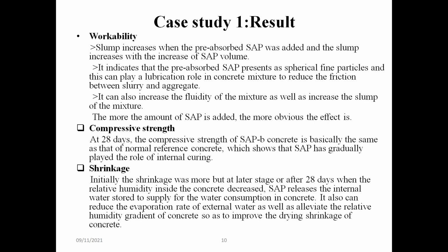Preparing the specimen according to the given specification, the concrete was poured into molds of 15 by 15 centimeter cubes, and they were subjected to the ordinary tests of workability, compressive strength, and shrinkage.